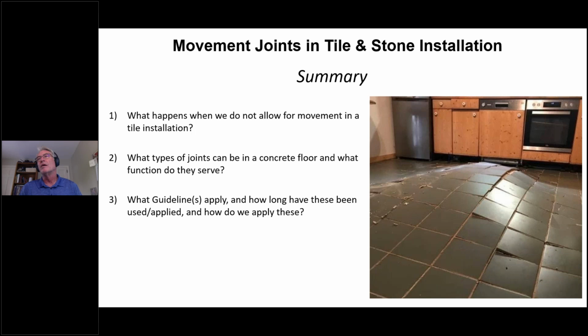I had a project in southern Florida that had 18 by 36 inch concrete tiles, like a terrazzo type tile, and the joints were 3/4 of an inch mortar and a little bead of sealant over the top. By the way, the reason I was on that job is it was failing, on a retail store, right over the sidewalk. Dangerous as heck. So they had to shut down the sidewalk and not allow people to walk through there, even because it was on the exterior. So it needs to be a full depth joint of sealant with backer rod, properly installed.